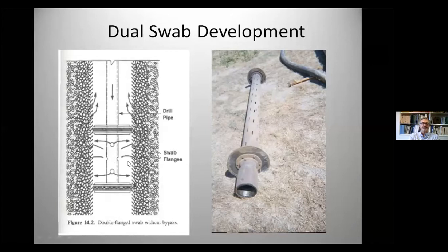In this manner, when this goes down to a brand new well, and is located, and you can place this on an end of drill pipe or drop pipe, you can flush fresh water out or dispersing chemicals out to break down the clays and silts. And it helps consolidate the filter pack while also flushing with fresh water through this type of zone. So this type of tool is best used when it's reciprocated up and down over, say, 1 to 2 meter, 3 meter intervals. So that way you're backwashing both on the downstroke, and then on the uppull, you're pulling that material back in.